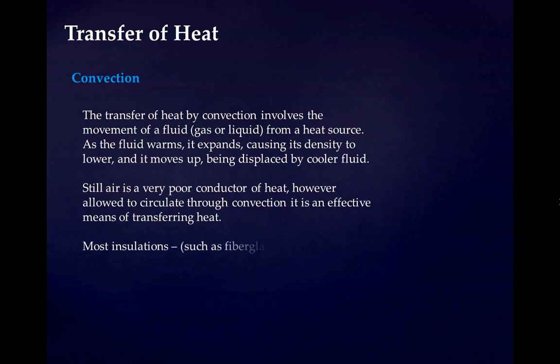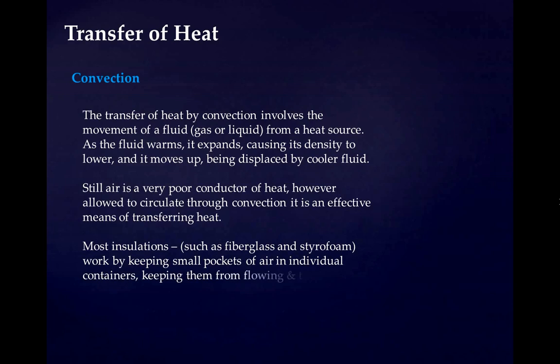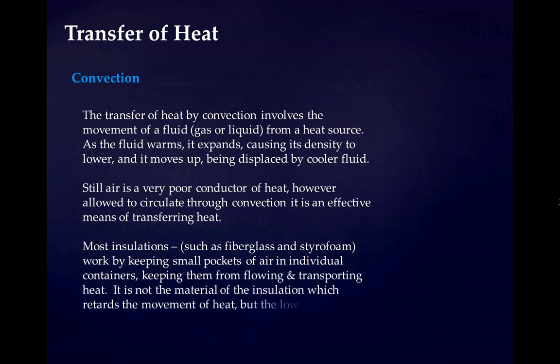Most insulations, such as fiberglass and styrofoam, work by keeping small pockets of air in individual containers, keeping them from flowing and transporting heat. It is not the material of the insulation which retards the movement of heat, but the low conductive standing air in the pockets.